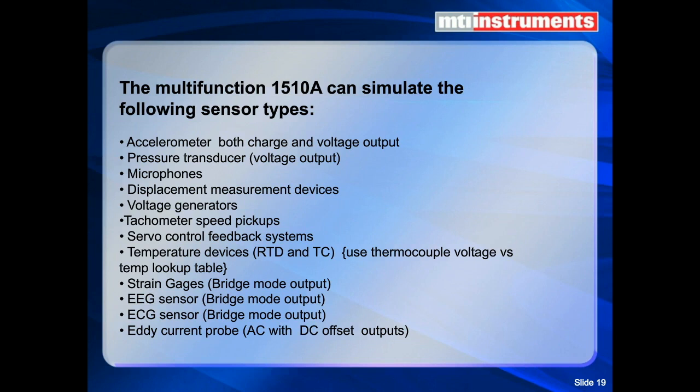The 1510A can simulate quite a large variety of sensors, and it's not limited to what we're seeing on the slide here. I'm constantly surprised by applications that customers have come up with, and sometimes they call us and ask us how to do things. Feel free to question us if you have an application where you don't see it in our user's manual or here. We already took a look at accelerometers. We can simulate both charge and voltage output. Some accelerometers actually have a little amplifier built in, so it's voltage out, so you don't need the charge.